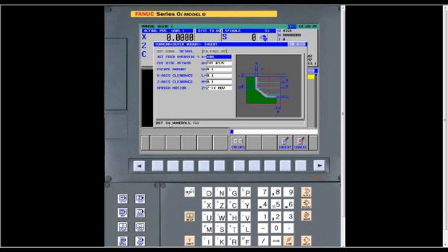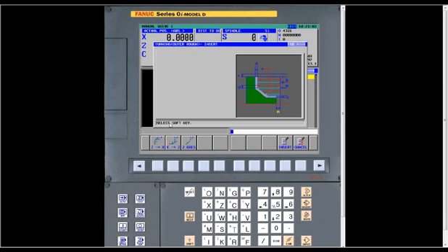The first one is first feed rate override. That's for like on a lathe, if you had something chucked up in hard jaws where it was running out, you'd have the capability of slowing down that first pass. Only the first pass. Then after that, it'll go back to your commanded feed rate. The cut rise method, that's for when you're turning over to a shoulder, when it feeds up to go back to the next move. You always want to use cut there, because otherwise it's going to leave big steps on a shoulder. And the rest are all just clearance moves, and then your approach motion like before.